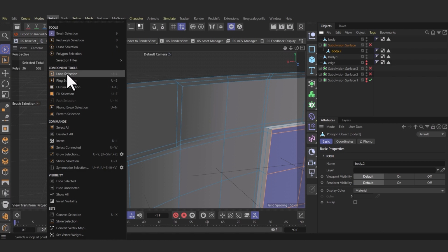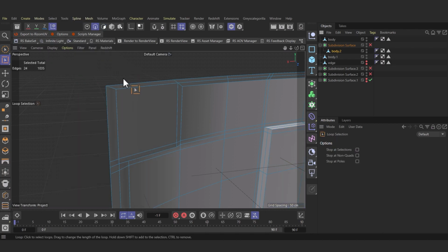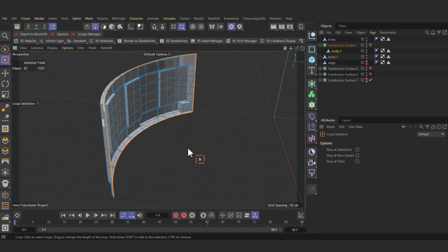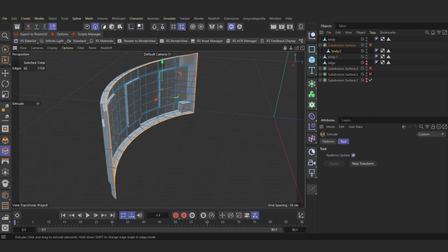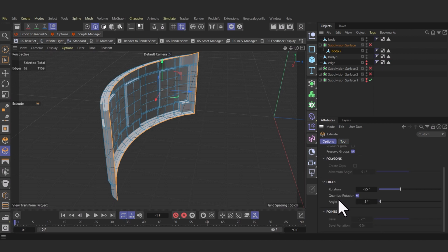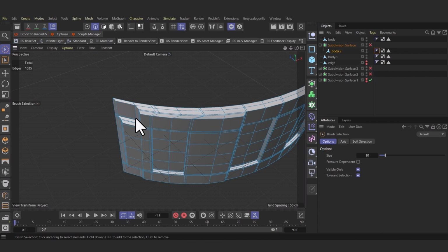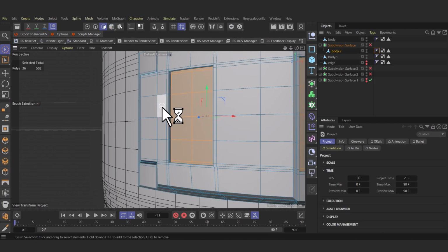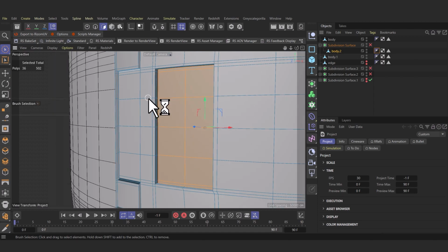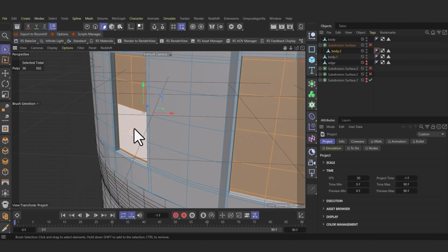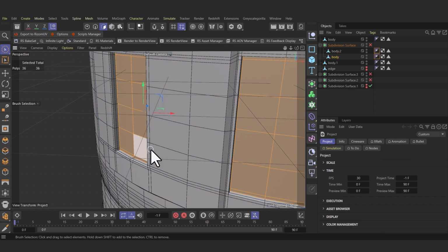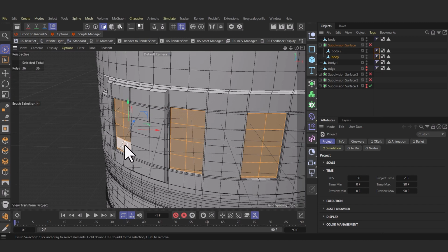I select the outer edge of the work and extrude it towards the inside of the body with this. If there's a small gap between the original model and this model, it will be filled. I select the surface of the three parts that I made for the location of the keys and apply the split method to give me a separate layer of them and then separate them. You can do this for each level separately.